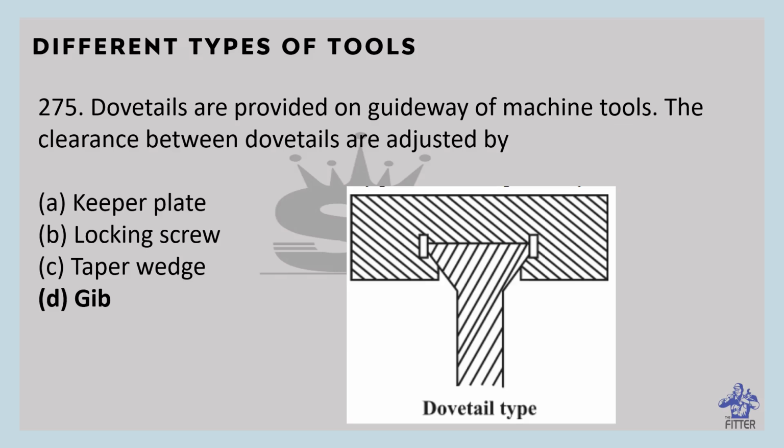In dovetail type guideways, adjustment for wear can be made by parallel blocks pushed by set screws. It features extremely high rigidity and alignment characteristics. It is an expensive guideway to produce because of this shape.